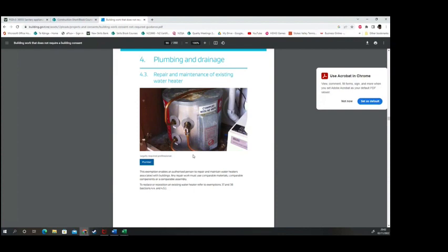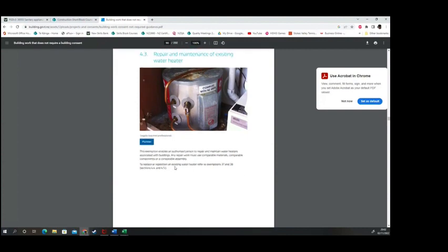Gas fitting is self-certified, but you don't have to get a consent for that. If you go from low pressure electric to mains pressure electric, that's actually a consent required job, although often it would go under the radar, which is technically illegal. If you got caught out doing that, you would have an issue.